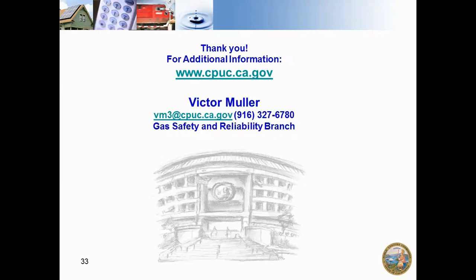They should not contain any gas. So if your facility still has natural gas in it, you're still required to do all of the maintenance tasks required by Part 192 on that facility. So your patrol, leak survey, cathodic protection, all of that has to be done until the facilities are removed from their source of gas and blown down and abandoned, capped off.